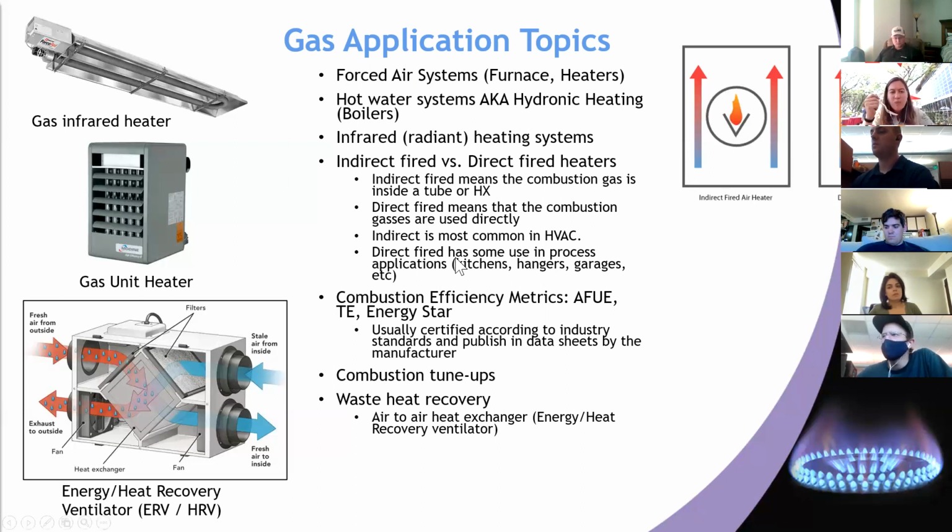Sometimes we'll see direct fired applications serving kitchens, sometimes hangars and garages, where you're not quite as concerned about the combustion byproducts in those. Those combustion byproducts really aren't great to breathe. And so with a direct fired heater, you'd be getting those combustion byproducts in the space. And so where you have a lot of leakage, air coming in and out, or a lot of turnover, then you're not quite as worried about that. But for most applications, people don't want to breathe that. And you can't guarantee that it won't be a dangerous level.